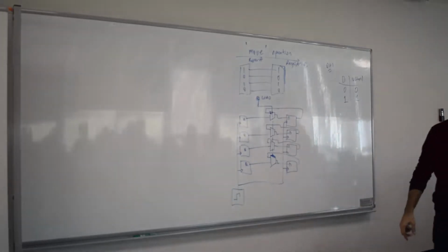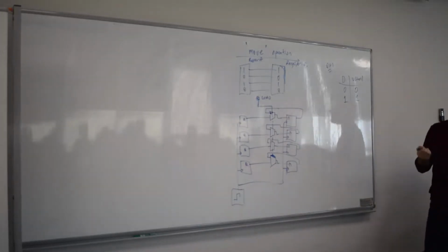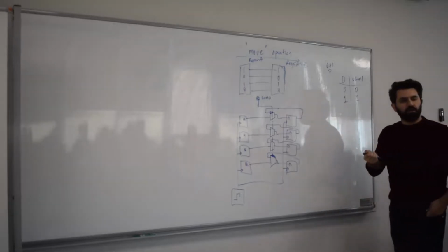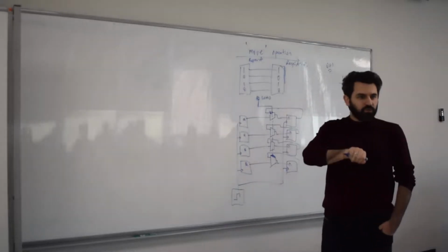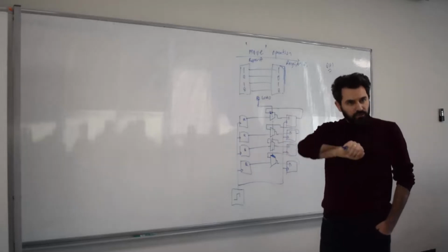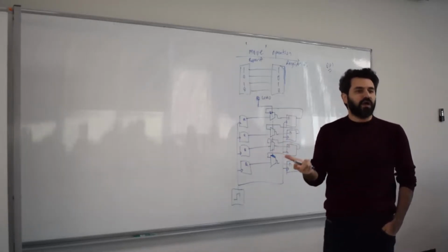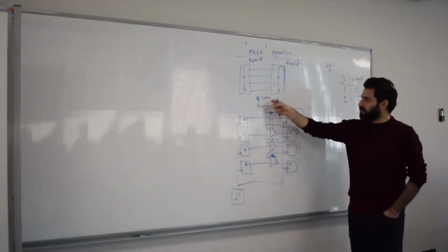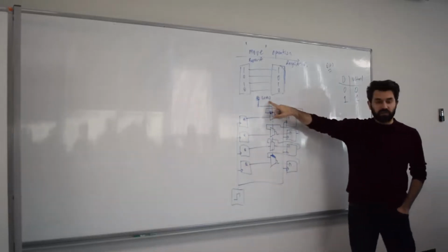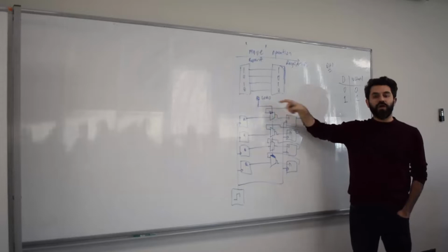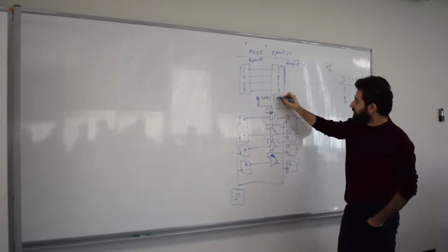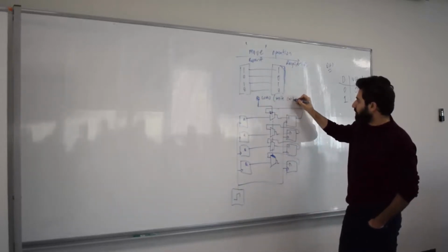You have to have a switch for your register, right? In order to store something, you open the switch, you write something, and then you close the switch, because otherwise your data will be corrupted with something else from outside. That's why we need to use a load, such a switch, that controls when we write something. This is actually the write control signal.